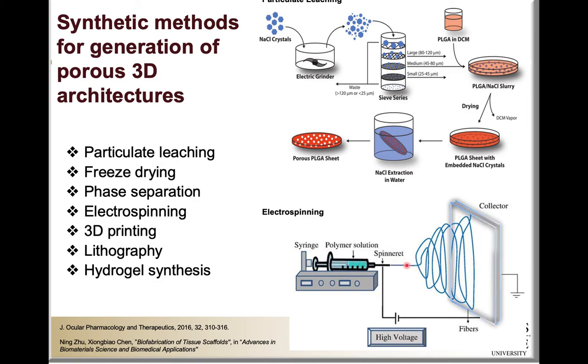And in the process, because we have a very fine, very narrow tube of polymer solution coming out, that undergoes very high transport, and basically the solvent is able to evaporate very quickly. And so once the polymer actually reaches here, what you have is solid polymer fibers. And of course, the solid polymer fibers continue forming and depositing onto that collector, and you end up with a mesh network of the solid polymer.